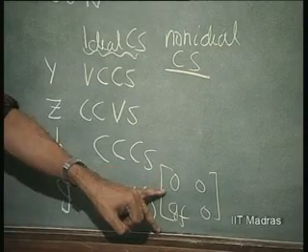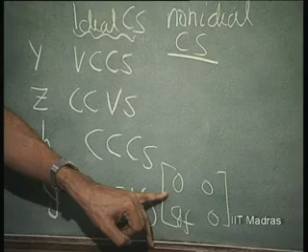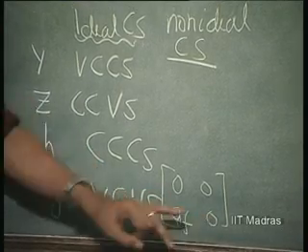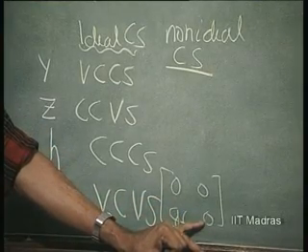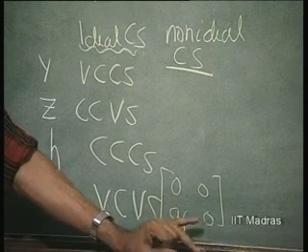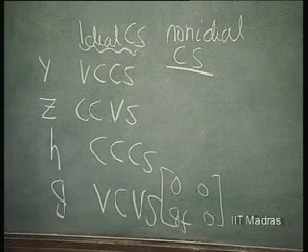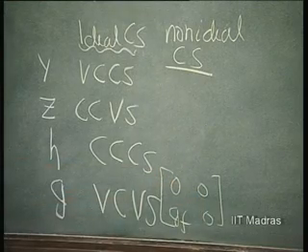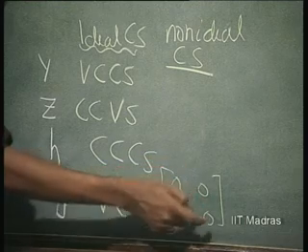That means input admittance is 0 or input impedance is infinity, output resistance is 0 since it is a voltage source, and the reverse transfer parameter is 0. Now, if it is non-ideal, these are non-zero factors. Close to a low value, this will be large, but these will be low values.